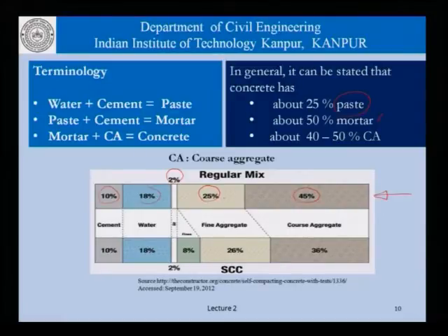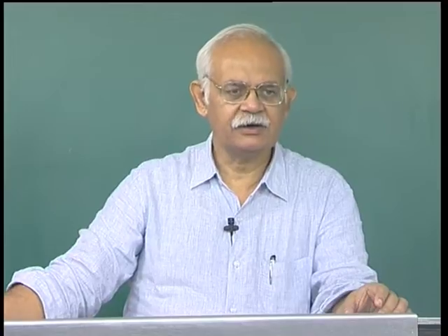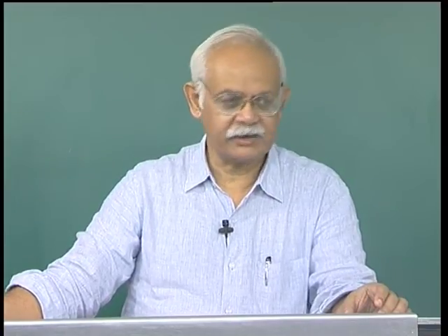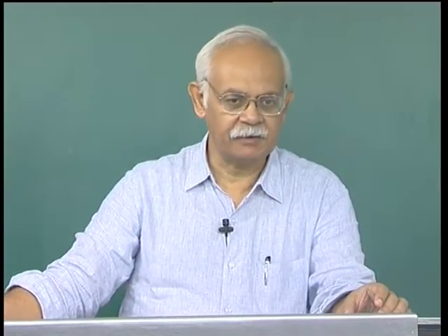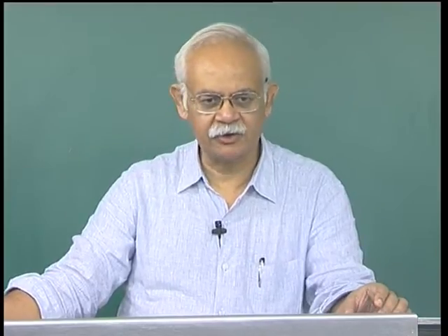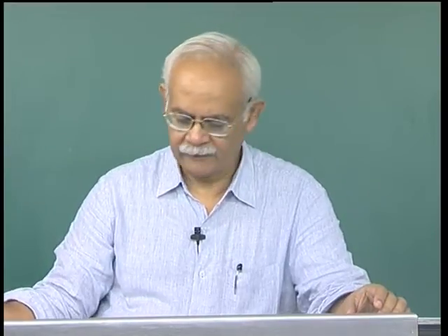So, coarse aggregate, in other words, just serves as an inert filler, an economical and a cheap filler in the concrete matrix, and that is a function which we must remember when we carry out any detailed study of concrete proportions, concrete materials, concrete properties and so on.